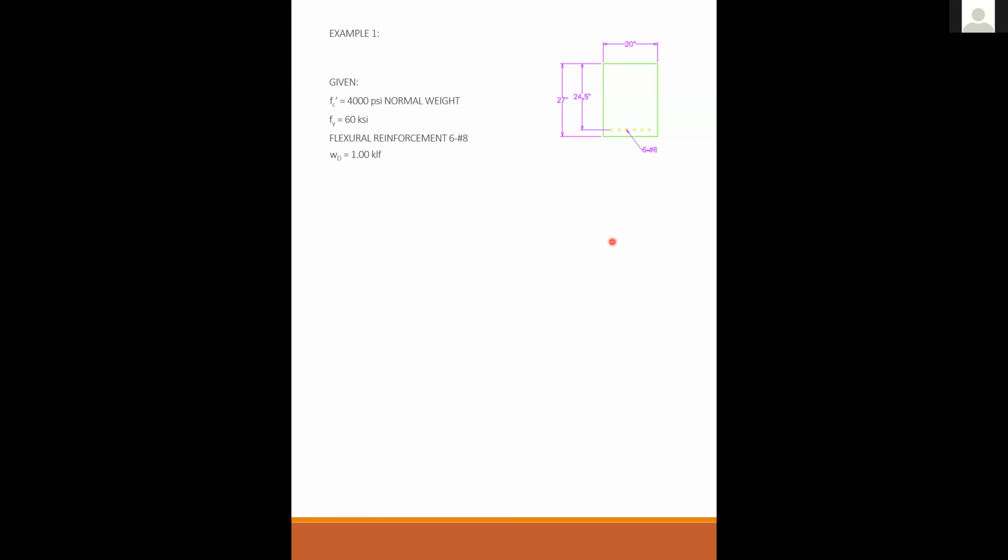Okay, let me say it another way. Hopefully this helps. Self weight of the beam is dead load. It's just one component of many components that make up the dead load. So if the dead load that you're given does not include the self weight, calculate the self weight and throw it in there, and now you have all the dead load. But self weight of a concrete beam is dead load. That's the definition of dead load. Okay, got it. Great.